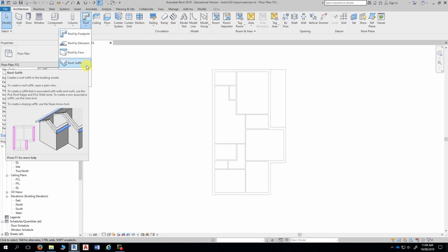Many years ago, in older buildings, the eave lining was actually made of asbestos. So if you are working on eave linings on older houses, be very careful. Don't drill or cut them. Get them tested. If they're positive, you've got to get a certified contractor in there to remove it. So if you're not sure, don't touch it.